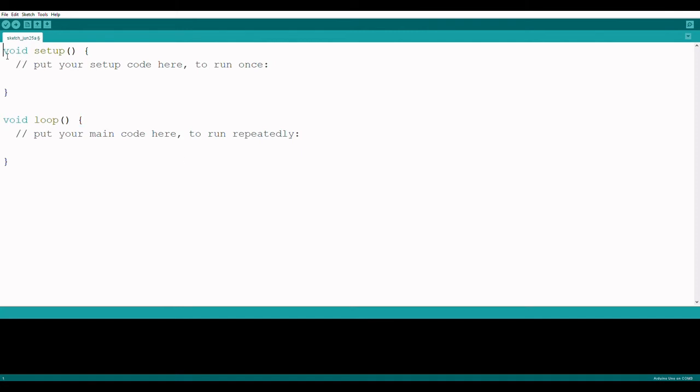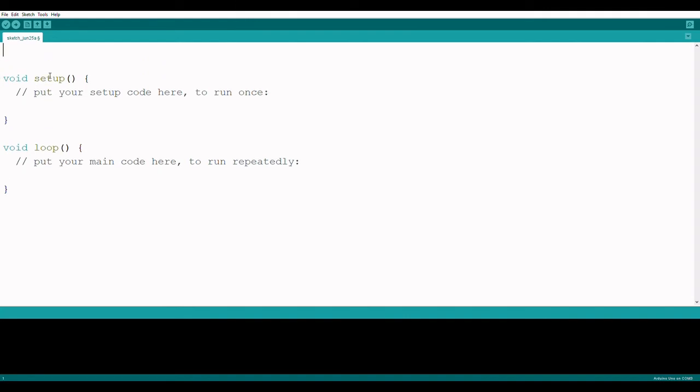So first off, we're going to let our program know what we have inserted into the Arduino, and in our case, on pin 13, we need the Arduino to provide energy. So we're going to let it know that we have an integer LED at pin number 13.